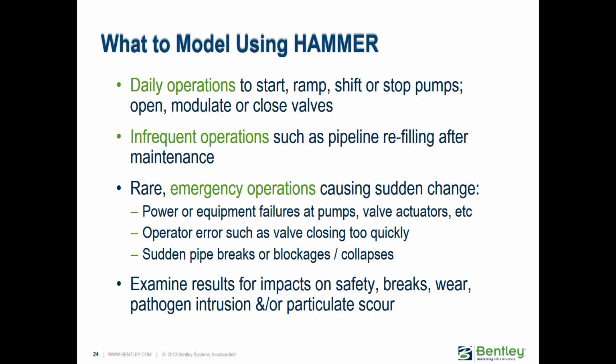And then you want to examine the results for the impacts on several different things. So as far as safety, breaks, wear. If you're seeing maybe the transient maximum pressure does not really get to the point where it would burst the pipe, but from the cycles of low and high pressure, it will induce some wear and tear on the pipe or the pumps.